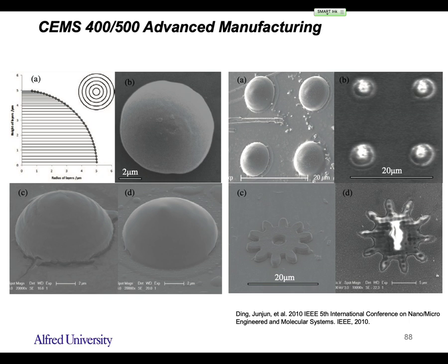Are you just using Cura for the slicing software? You can use Cura, but you can use other software. I think it's Slic3r. That's open source software that's also quite powerful. Cura is really straightforward. You don't need to tune a lot, and you can get a good working G-code. So if you are not experienced, I would recommend you use Cura. But if you want more control, you can take a look at Slic3r. There is a lot of really helpful documentation online. I recommend you do your self-study on that.